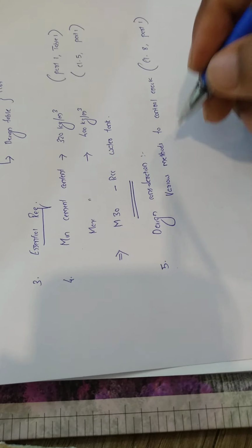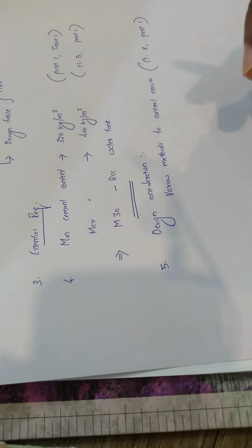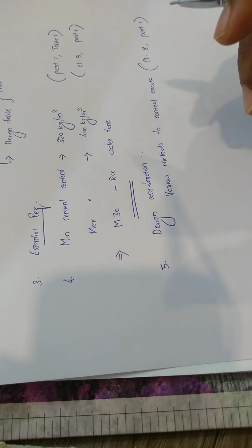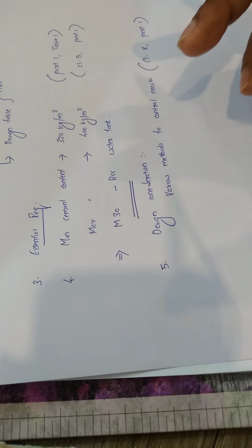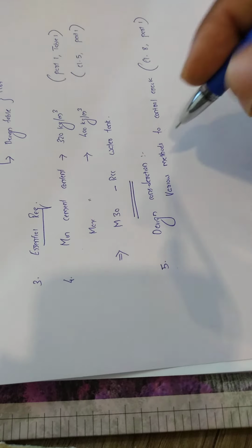There it is given as correct placing of reinforcement, the importance of small size bars, the usage of deformed bars, then avoiding the use of thick timber sections as shuttering, which essentially prevent the flow of heat of hydration, and also permitting some expansion and contraction through proper joint detailing.